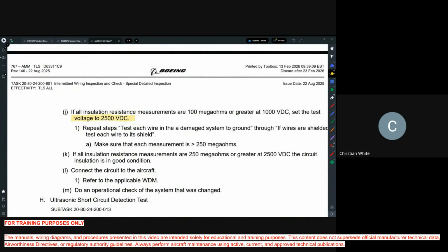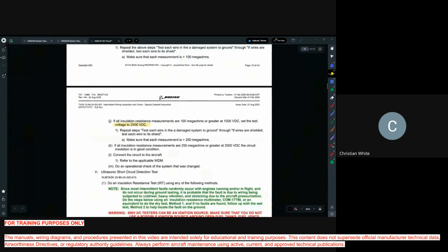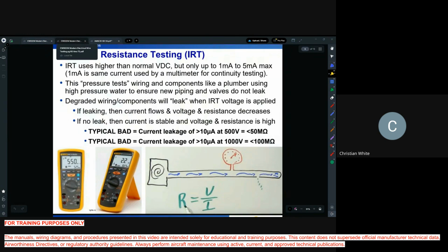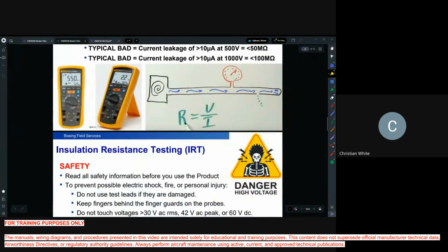Anyone that's done this testing, the meggers we have, unfortunately, right now only go to 1,000. But the one specifically that you will probably come across, I think Atlas has a couple, is the MIT 2500. That one does go up to 2,500 volts. Maybe I'll do a class on that at some point. But if you need more, call me and I can walk you through how to use that.